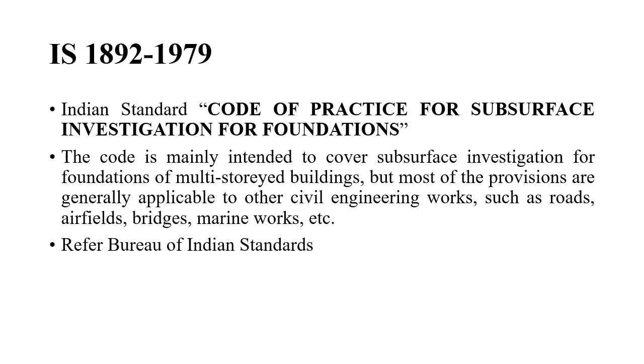See, when it comes to the exploration of the subsoil profile or subsurface exploration, the most important code for an engineer is IS 1892-1979. So this is the Indian Standard Code of Practice for subsurface investigation for foundations.